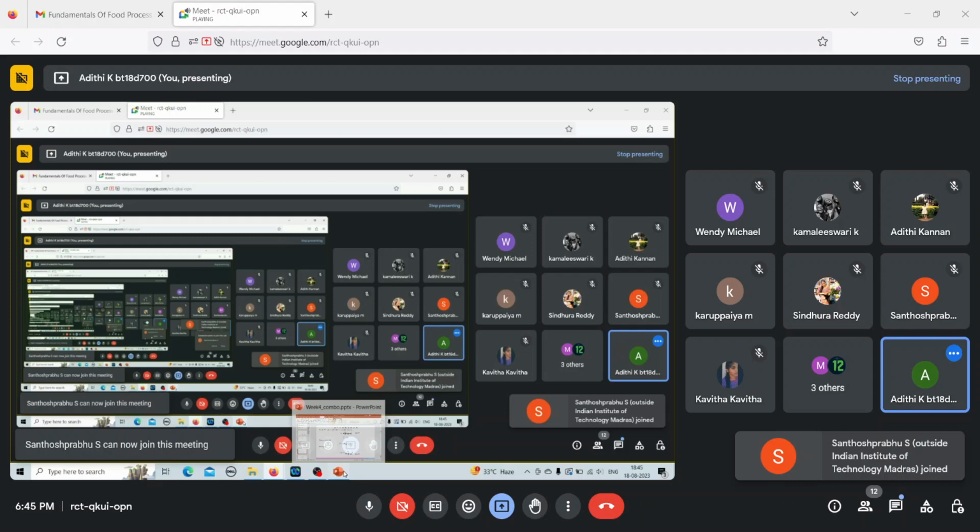I am repeating again, the feed will fall from the top to the bottom. By the time it falls, it will get heated up by the steam. By the time it reaches the bottom of the evaporator, it will already be at its boiling point. So whatever concentrated liquid you get, you can collect at the bottom, and the vapor that is now free to move will pass through this area and can be collected separately.